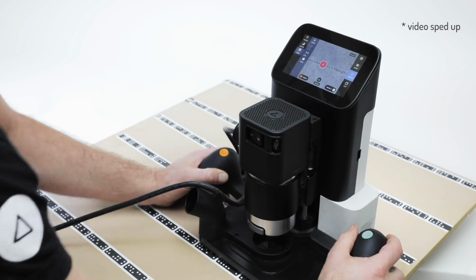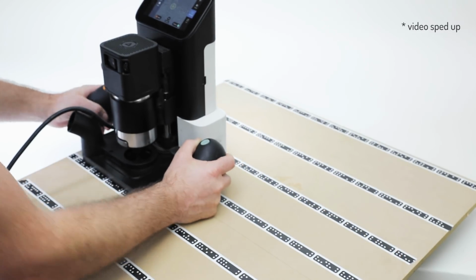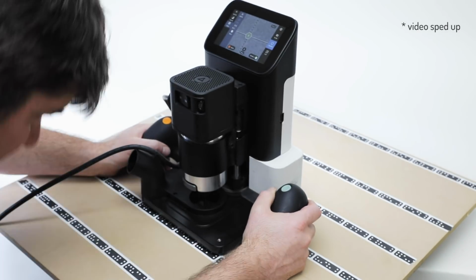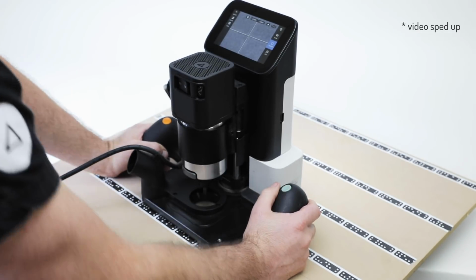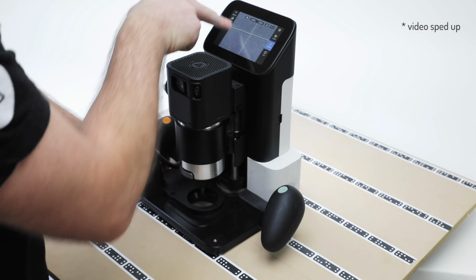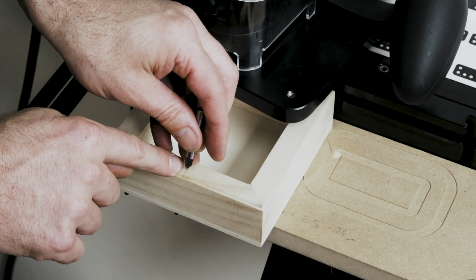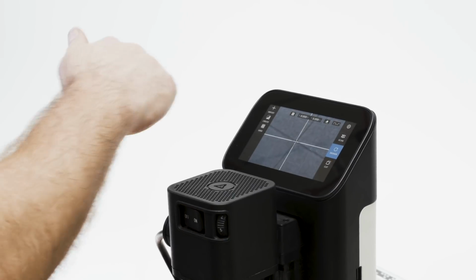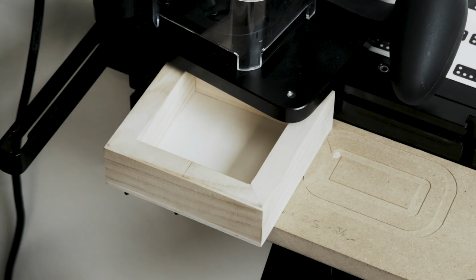There's also the entirely visual approach. So if you had a chalk mark in the middle of a floor, you would probe 3 times with the point of an engraving cutter hovering just above the surface. So you would do the same thing using the center of the cutter as your reference point, looking at this, not the screen. And then there's a shortcut, which is just a double click to get you a fast grid at the very center of the cutter itself. And that's the 4 methods. So we'll go through them now.